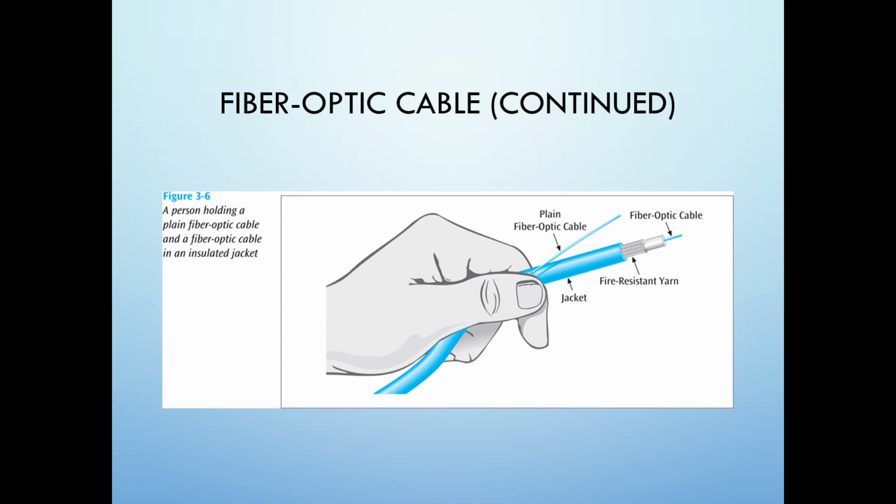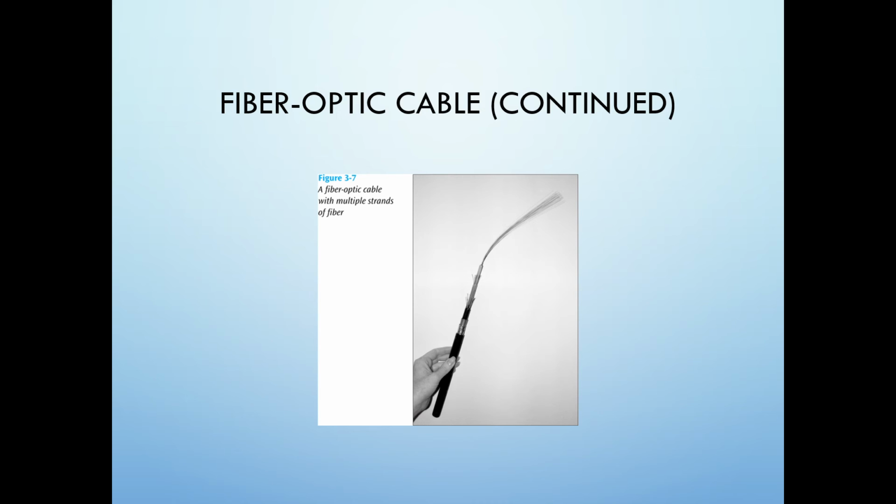The laser is much more expensive than the LED, and it can produce much higher data transmission rates. Fiber optic cable is capable of transmitting data at more than 100 gigabit per second over several kilometers. Because fiber optic cable transmits non-conducting photons through a glass medium, it is impossible to wiretap. Also, because fiber optic works with light, it is immune to electromagnetic interference and noise.